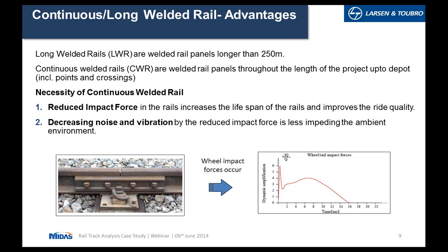The advantages are quite obvious, that CWR enhances the life of the rails and the wheels, as well as it improves the riding comfort, riding quality, and also considerably reduces the impact noise and vibration which are caused due to the fish plate joints.